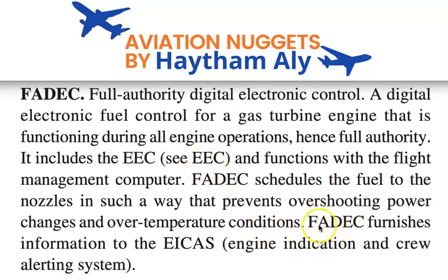The FADEC or EEC always sends primary engine data to the EICAS or ECAM directly. What is the primary indication? Like engine pressure ratio, N1, N2, EGT, fuel flow.